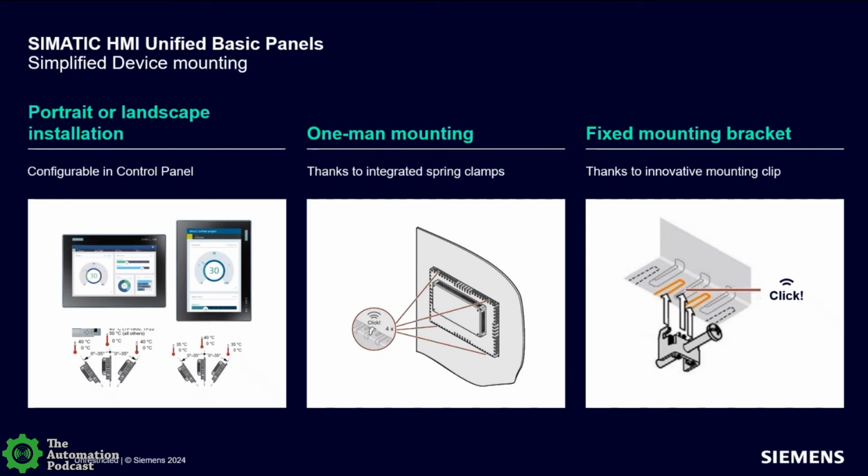And then just to round out today's conversation, we've got different mounting capabilities. You can mount it portrait or landscape mode, so you can have different angles. Just check the tech specs on the device to verify that you're within the temperature ranges, because any tilt of the device changes the airflow that we've designed for cooling of the device. Just stay within specs on that. But we can mount these devices vertically in a portrait mode if that suits either the physical restrictions or maybe your application just views better in portrait mode.